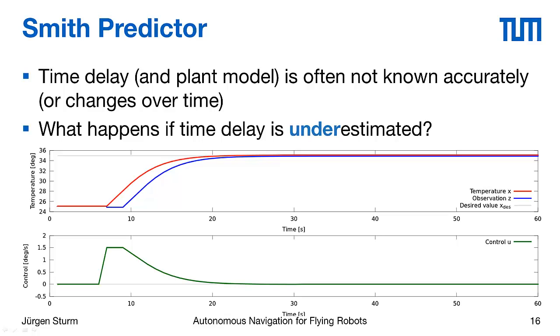But in this way, you can use your model to compensate for half or maybe 90% of your time delay, and you consider the rest as the noise or the thing that you try to not model and just use directly the sensor readings. This leads, of course, to a slightly slower convergence in the end, but it circumvents oscillations and makes you approach the goal state nicely.